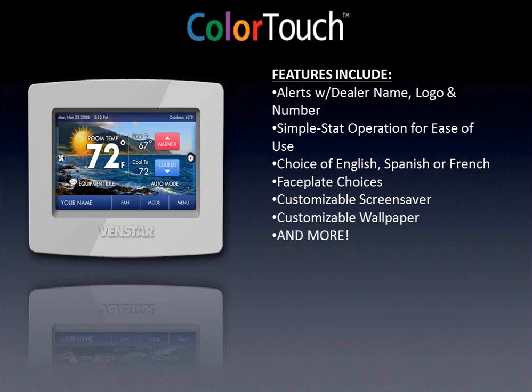Typical alerts are the usual things like filter changes and stuff like that. But you can also set up alerts for high temp and low temp. So if this is a vacation home or the people are snowbirds or something like that, you could set it up so if it drops below, say, 50 degrees, they'll get an alarm so they know their house is about to freeze. So there's some stuff like that you can do.